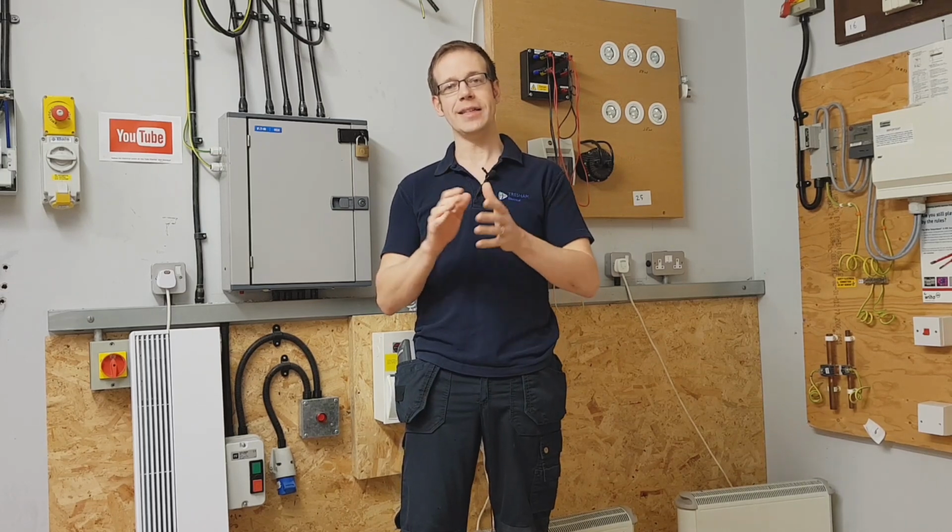However, what we're going to explore in this video is what happens when you've got an imbalanced three-phase load. Now again, imbalanced means that you have different amounts of current inside each conductor. So we're going to set up our test rig with an imbalanced load. We're going to measure the currents in L1, L2, L3, have a look at the current in the neutral, and then we're going to have a think about how we get from that imbalanced current to our neutral current and how we can calculate it.